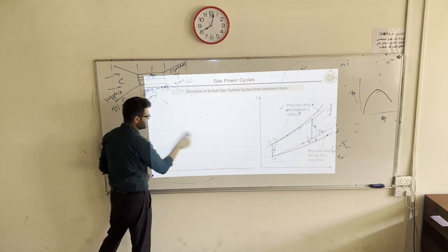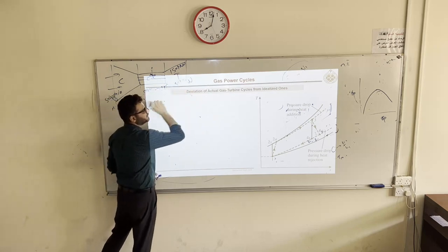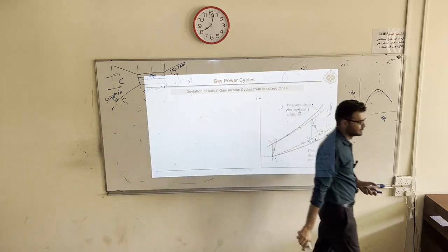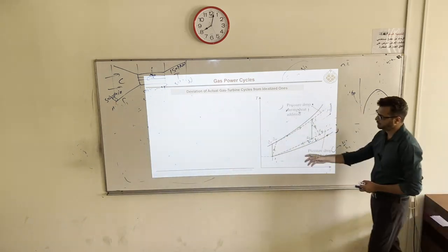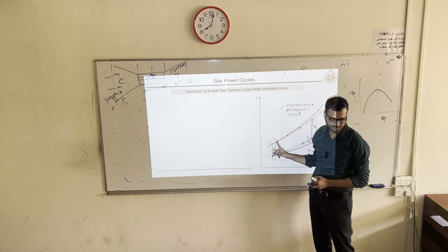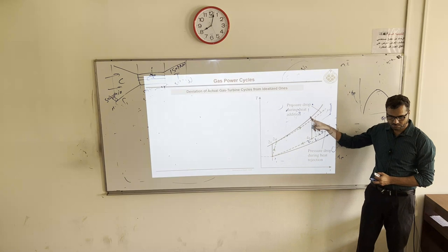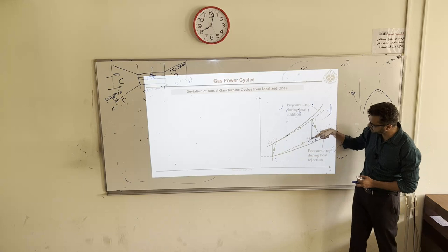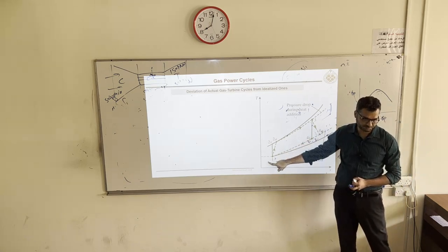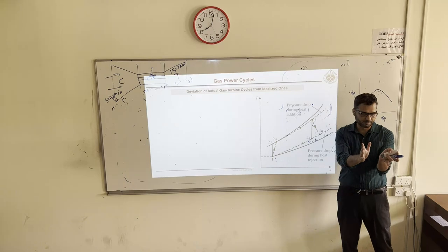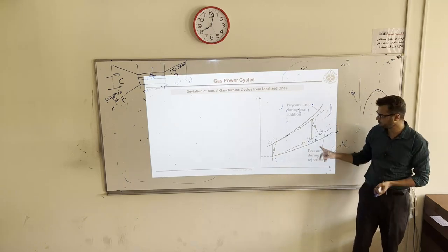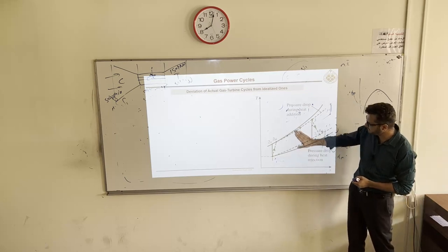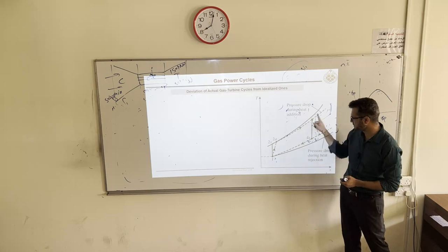So let's come back to the cycle. The ideal cycle, but actually everything is not ideal. Every process has irreversibilities. Like in the compressor, we already know isentropic, this is non-isentropic. Similarly, turbine isentropic, non-isentropic. There is also a pressure drop during heat addition, and also pressure drop during heat rejection, when the fluid is flowing through the combustion chamber or when the fluid is cooling down. So there will be such pressure drops. But normally we neglect these two effects, but we do not neglect these two.